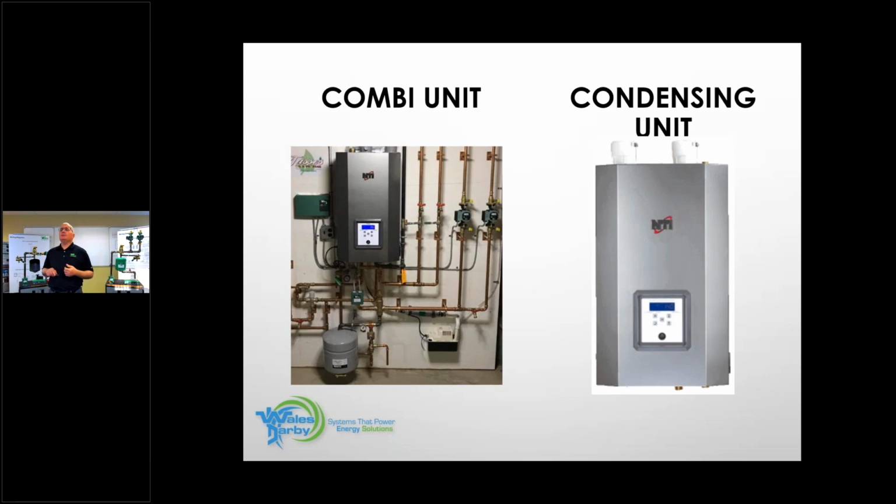Something to think about when we just talked about recovery for hot water, and John was talking about turn down ratios and things of that nature. When you're doing a combi unit, don't oversize it there also. You don't want to make it so big that even when there's a call for space heating, the unit's too big.